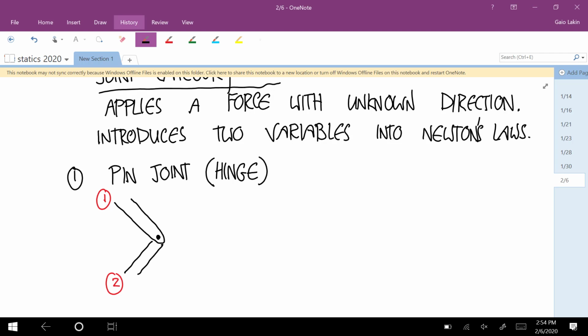And I have a pin joint here. Well, there's a lot of friction, but imagine there's no friction there. Say the top one here is the object that we're analyzing, and I'm imagining this other one is fixed. Can you find any axis where I'm prevented from translating this top body? Yeah, any axis you choose, you can't translate it.